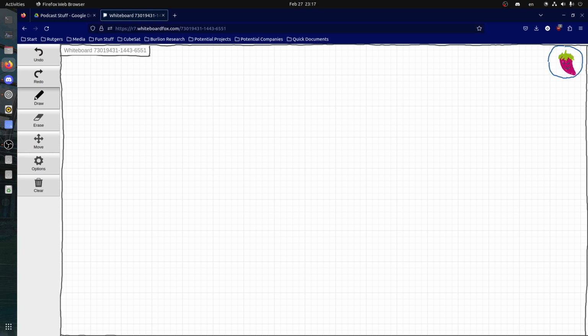All right. So yeah, I'll start with a quick overview of the ADCS, and then the main components, the main software and algorithms used, and then we'll get into the questions. An ADCS has the job of determining the attitude, that is the orientation of the spacecraft, and then controlling it to point in a desired direction.